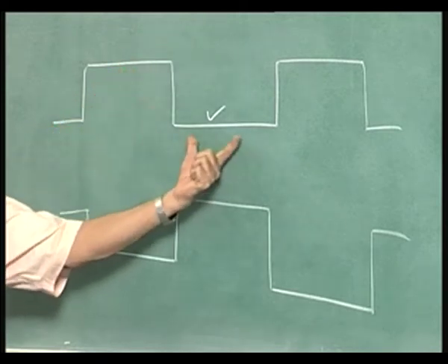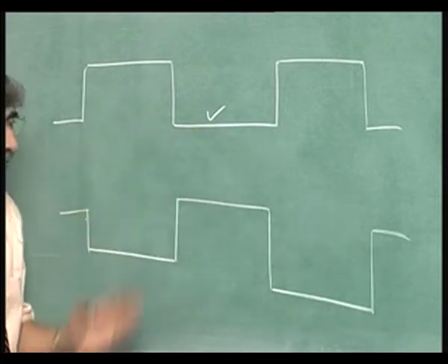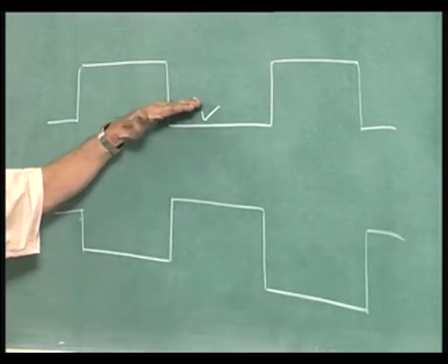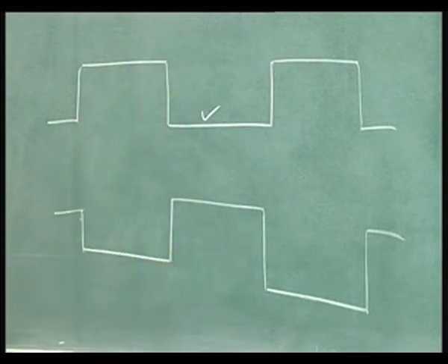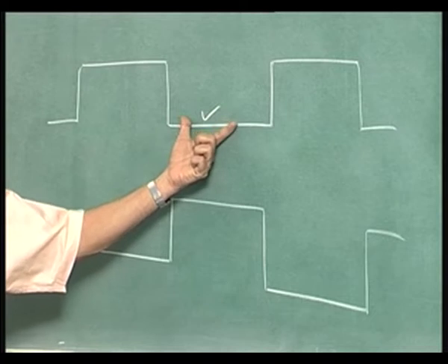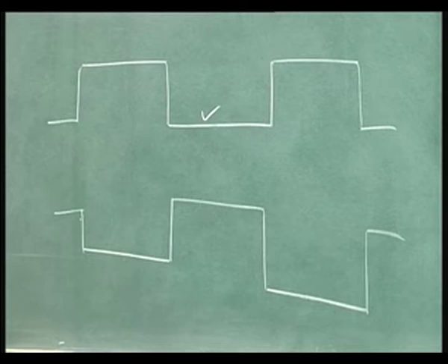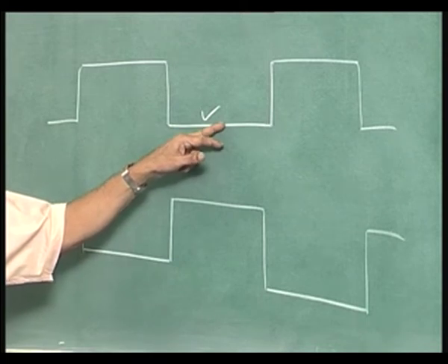Now, when you have a potential well like this, and if this well is narrower, then you will not have continuous energy levels, both in the conduction band and valence band. You will have those energy levels quantized, and this will be called a quantum well. Energy levels are quantum levels, just like the energy levels of an atom are discrete in nature. If I put an electron there, it will have discrete allowed energy levels.